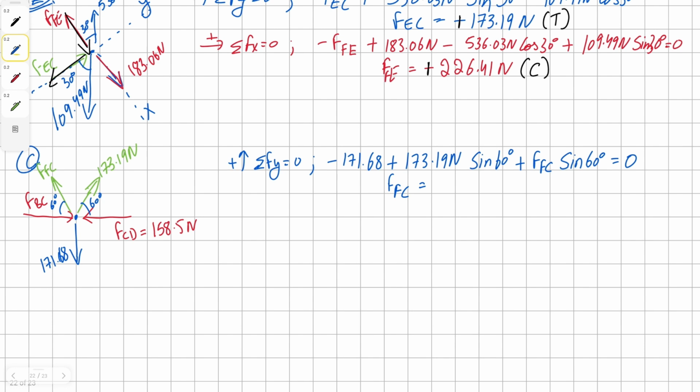For FC, we get our solution as 25.05 Newton, and then it's in positive, therefore we know that this member is in tension.